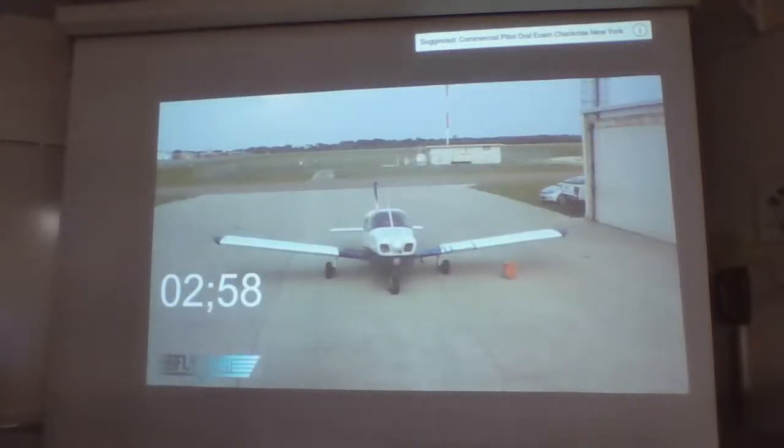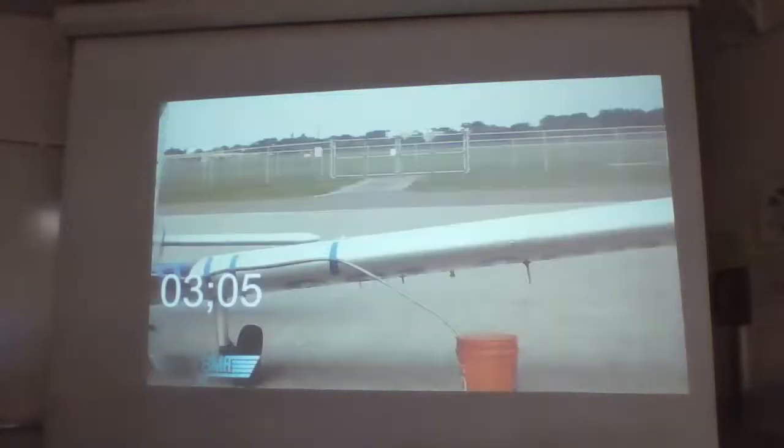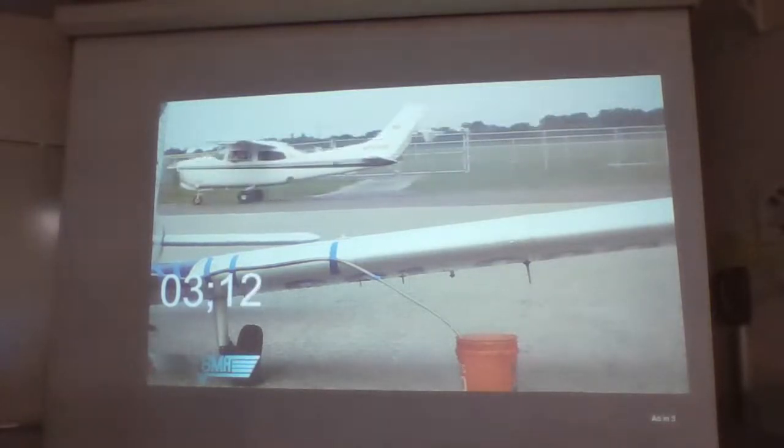We see about 1350, 1300, still producing some amount of power. This is still better than just gliding like a stone. This is definitely some amount of power being produced here, 1300 RPM, when we're not moving through the air at all. Probably a little over 100 pounds of thrust. Keep in mind that this airplane makes about 400 pounds of thrust at most. So still over 25% power is what you have available to you right now if you were in flight. This is shaking pretty good, though.